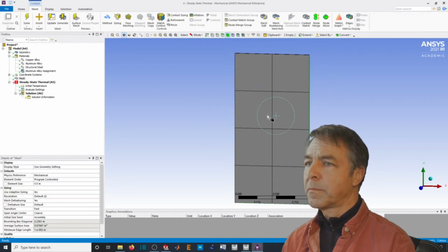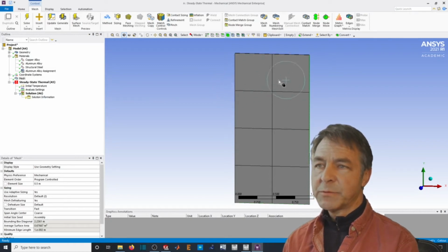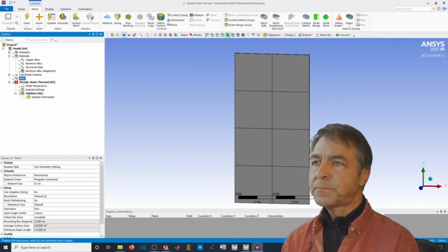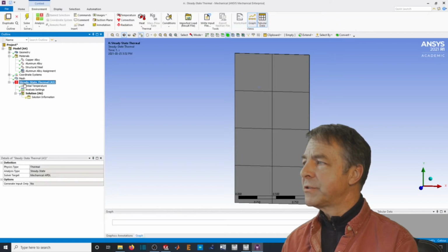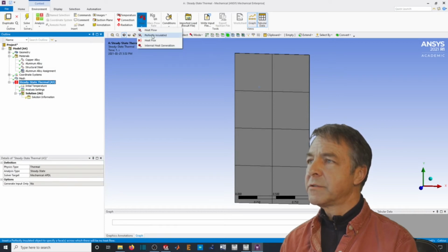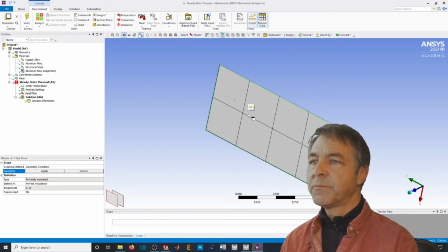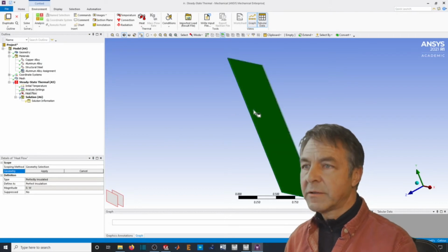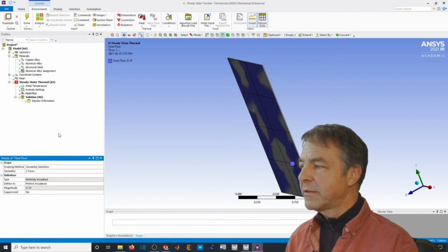And there's the mesh, and you'll see as you scroll over it that the rough size of the mesh is shown by the circle that you scroll over. Now, if we're happy with that, that's fine. We can set up boundary conditions. So we select the steady state model, and you'll see, first of all, that there's boundary conditions, and we want to make perfectly insulated for this face and this face. Oops, we have to go Control Select. There, we've got the two outer faces are perfectly insulated, and so those are selected.